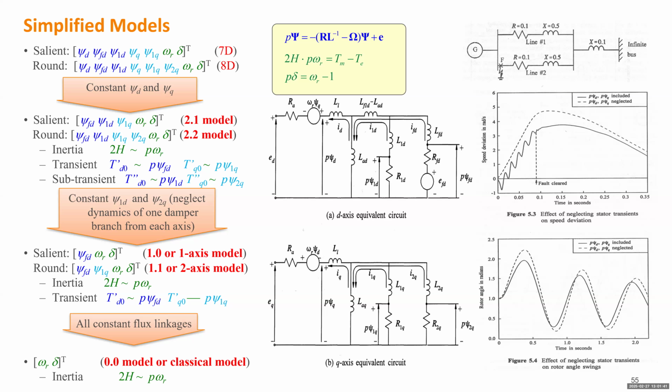For instance, you have a power grid with a lot of synchronous generators and also renewables connected to the grid as inverter-based resources. You have a very accurate inverter-based resource model, like an IBR model. But you also want to study how the generator interacts with those IBRs, but your study is focused on the IBR, the renewable, not on the generator. So you can somehow use a simplified model from this list, but you have to simulate in three phases, okay? Maybe some reviewers will be fine with using those models as long as you don't want to study the detailed dynamics of the generator, okay?